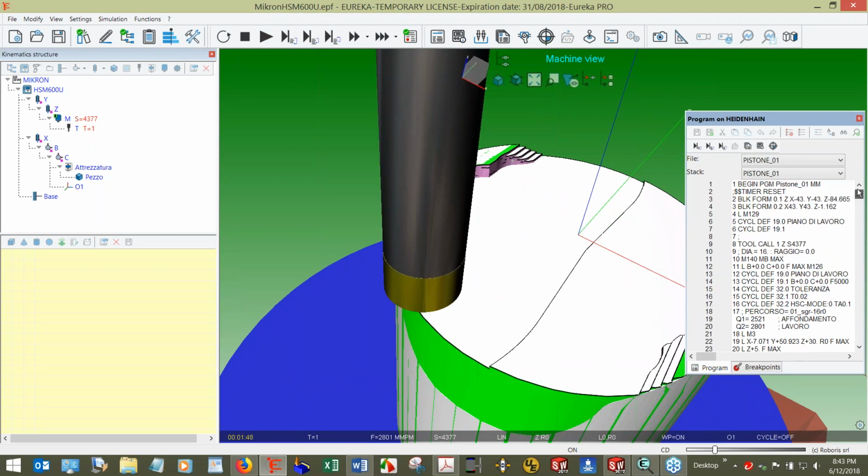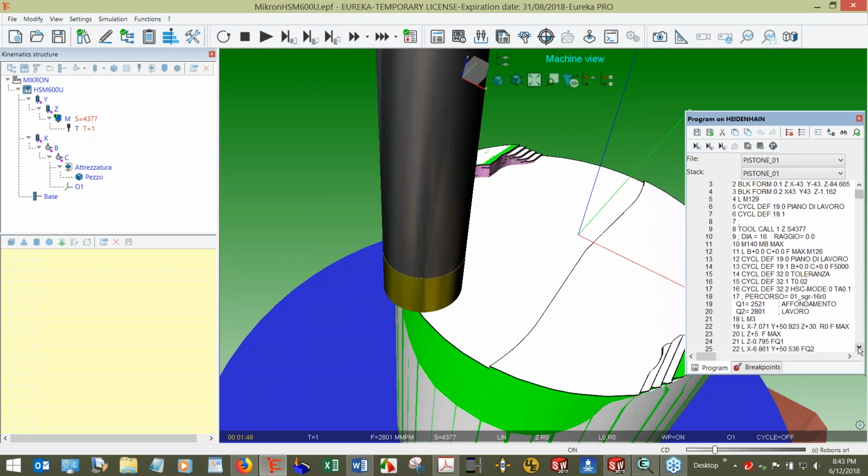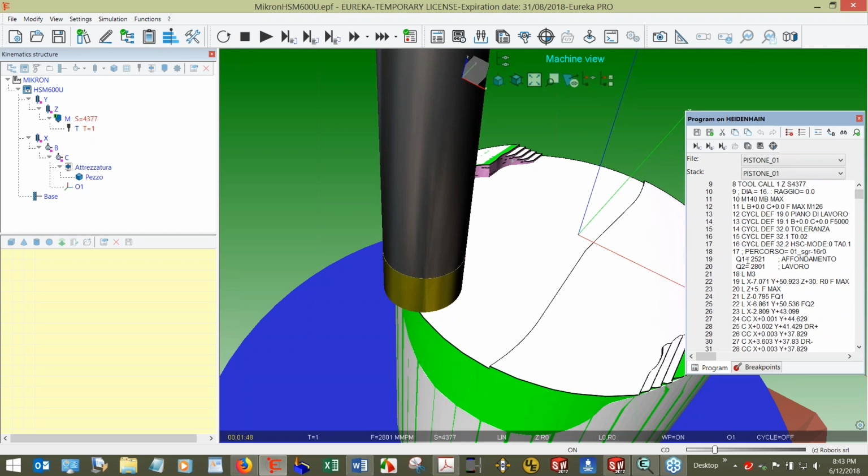So this optimization, right now, is running about 4,300 RPM, and this is some kind of crazy code. It took me a little bit to look at it, but this is in millimeters per minute. It's 2,500, so it's running about 64 inches a minute.